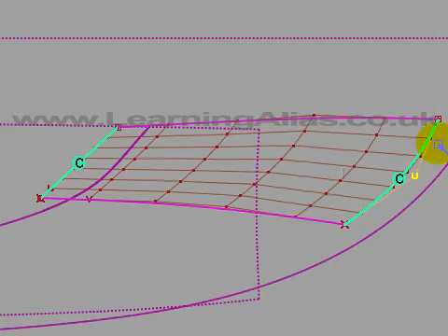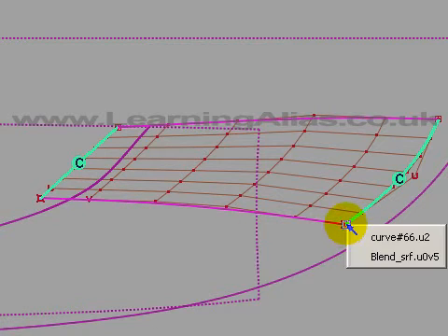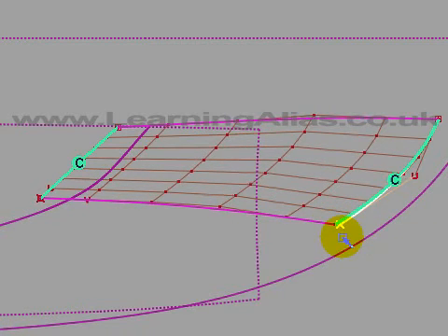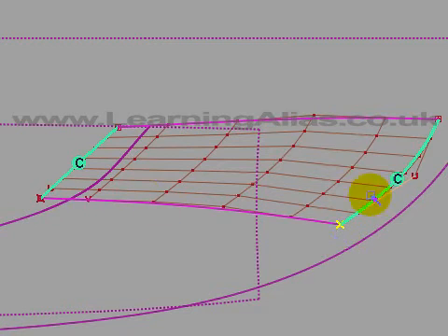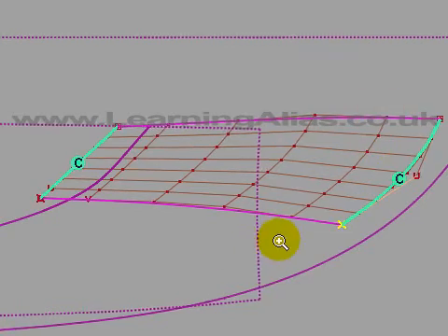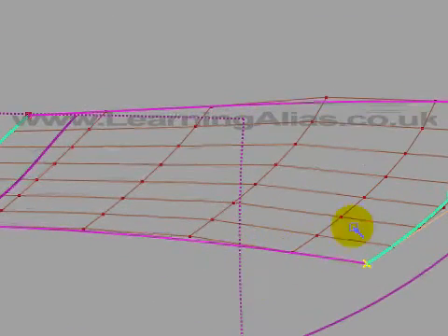So we shape that to an imaginary curve, and also we know that this one here is going to have some curvature in it. So let's adjust that. I'm looking at the CV structure and making sure that there's no kinks or glitches. You see, we've got nicely arced CV hulls there, which is what we want.